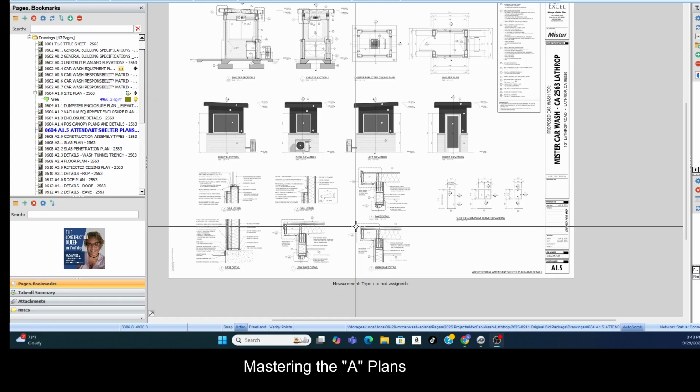You're going to need a section view, a section of that roofer, a section of that wall framer from top to bottom, so you can see a section of that wall insulation person. Okay, plywood, anything. So we go from plan view to section view to detail view. The more detailed, that's the final view. You can't go any lower than detail view.